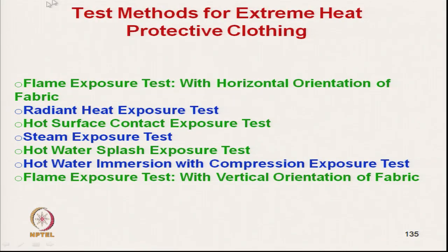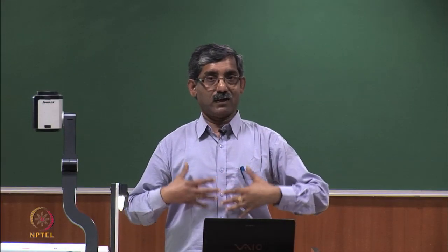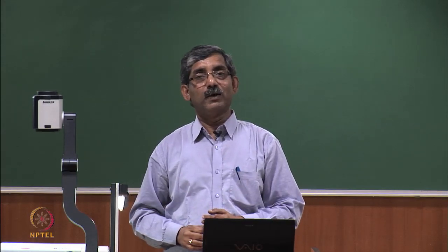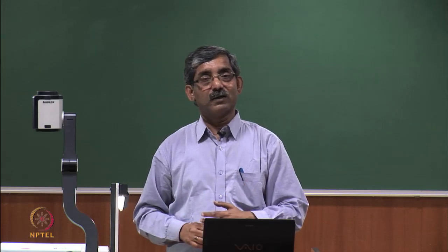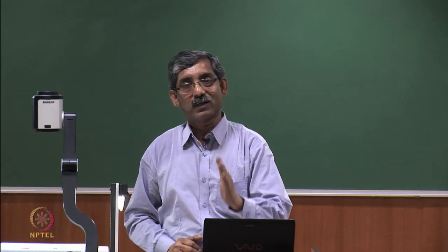And the last method, as I mentioned, the first method was the flame exposure with horizontal orientation, and the last method is the flame exposure test with vertical orientation, where the fabric is in vertical condition, because in most applications we have seen the fabrics are in vertical condition. So, in this test we can measure the heat transmission through the fabric under flame exposure in vertical orientation.